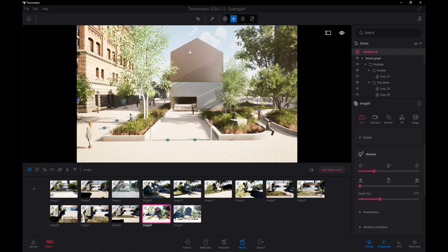And if you notice here, again, the fog is helpful because when I go to the Photoshop side, I'm going to show you more of the post-processing. I want a slightly textured look to this, and the fog gives you that. It's not hard to tell. Let me show you. If I turn it off, see, things are a little bit more sharp and more clean. I actually want it to be a little bit textured, a little bit dirty, right? So that's why I add a little bit of fog to this. And again, these views, the elevation views, help the most with what I'm going to show you for the post-processing.